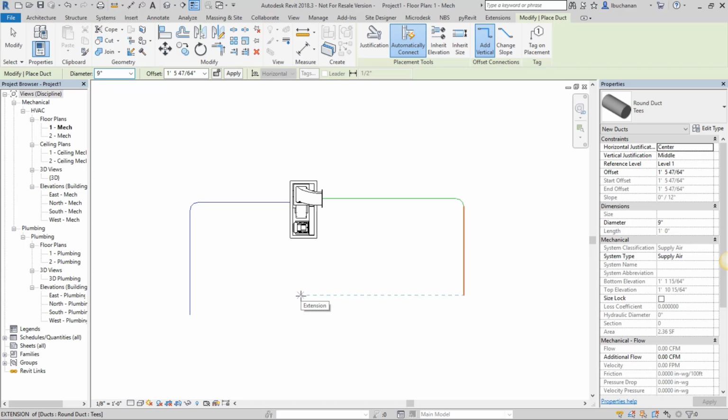That can absolutely be set up on the Revit side or in the Inventor side and then exported out to Revit. It depends on where you want to do the data. The designer may want to see some type of symbol for an air handler unit, which could be as simple as a square box with an X through it, depending on what that symbol needs to be. Or you could just make it a square box, and you can include that either on the Revit side or the Inventor side, like I said before, and then it will show the level of detail change when you change it from a coarse detail to a fine detail.